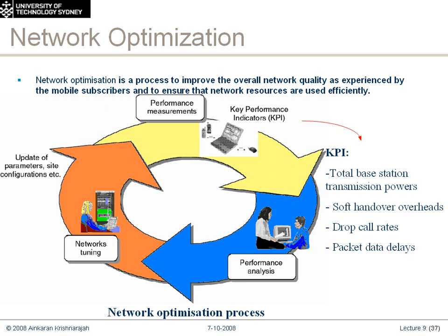That effect is called a ping-ponging effect, and the ping-ponging effect happens in all mobile networks, actually, GSM as well as wideband CDMA. So what tends to happen is you want to try and avoid those situations. And if a lot of subscribers are undergoing a ping-ponging type effect in that region, then you know something's quite wrong with the planning.